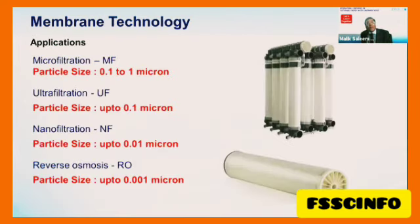In membrane technology, we have 4 types of membrane: microfiltration, ultrafiltration, nanofiltration, and RO. You can see this is basically a molecular sieve, and you can see what pore size they have. They will not allow particles bigger than this pore size to pass into the water. And these are the pore configurations, and based on their application, we select which type of membrane is to be used for microfiltration, ultrafiltration, nanofiltration, and RO.